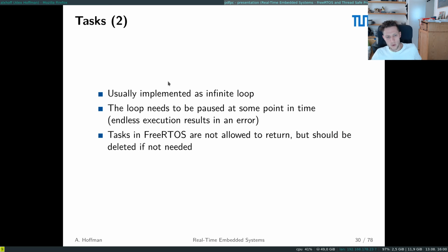So then how we actually implement a task is always slightly different, but on FreeRTOS, a task is a function, and a task is essentially just a loop that should get executed forever. So if you wanted to implement the network I/O loop, you would just have a task, which is some function, and the function you pass to the function that creates the actual task.